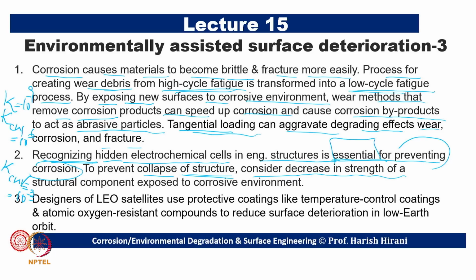So, can I multiply that corrosion-related factor with the strength of the material? At the beginning the strength is something like 100%; after maybe 5 years the strength will be 90%, after 10 years 80%, and then there will be some sort of line, or threshold. Below this line we should not use the equipment; we should disintegrate the complete bridge or complete ship or complete plane and come up with a totally new system. The life can be analyzed when we have those factors available, when we have an understanding of those systems also.